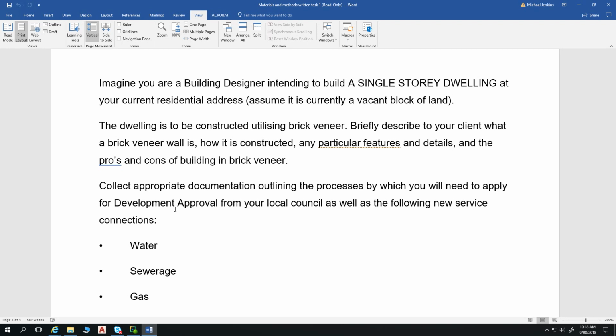That's what holds the roof up. That's actually providing the wall structure and holding the roof as well. And then in this plane here, if we look at elevation, we would see bracing happening there as well. So that's to stop the wall frames doing this. So this is what's carrying the load.